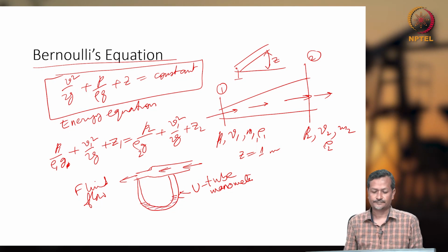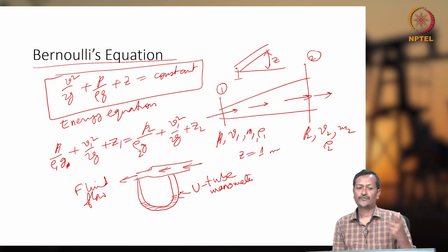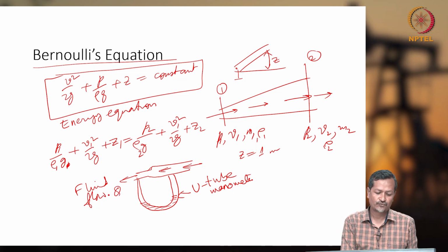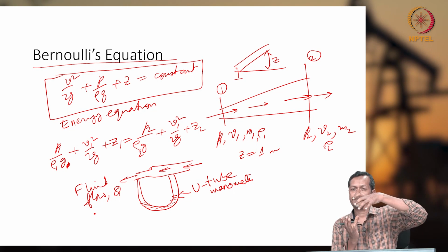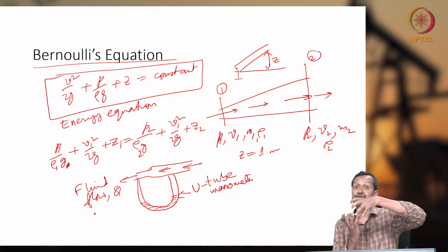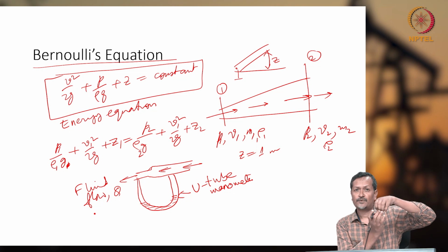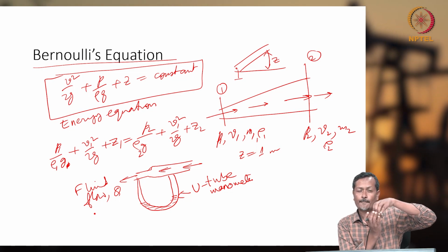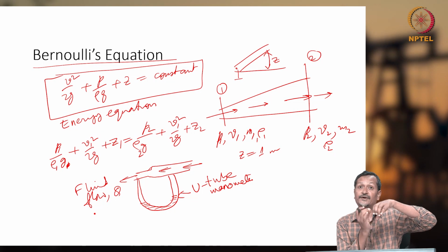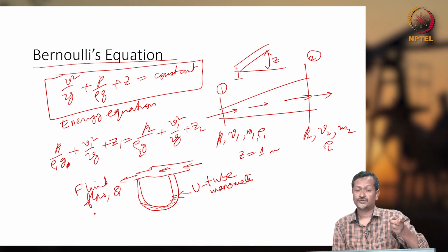Now, if fluid flow starts, let's say Q flow rate you are giving. So what will happen? The larger diameter pipe section will have low resistance, low pressure, but smaller section will have higher pressure. Same flow rate you are getting, but if velocity is changing, then your pressure is also changing.